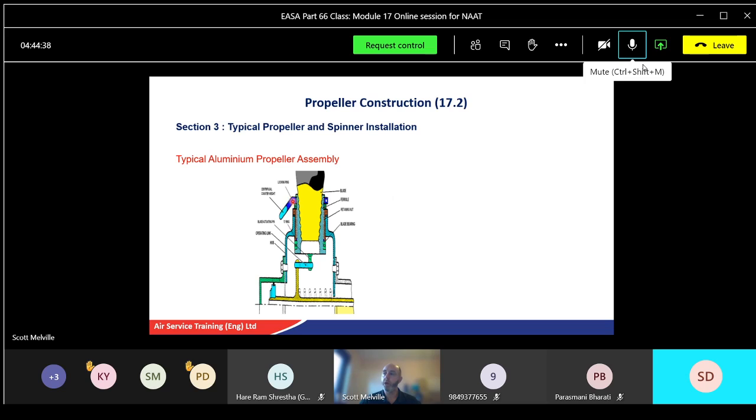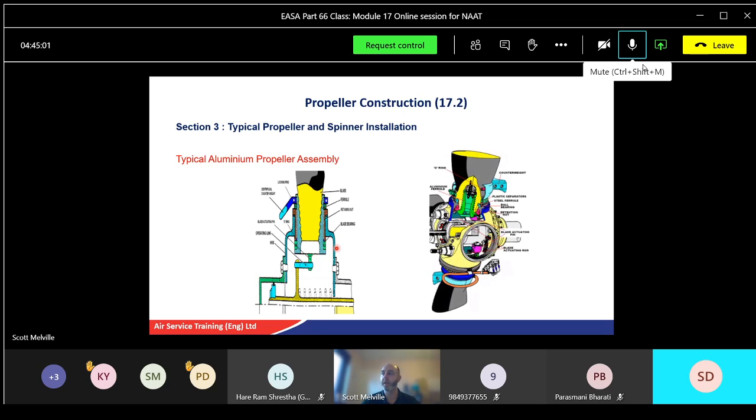There's your counterweight, and there's the locking ring. And you'll have your other bits of your change mechanism, and so on. There's the blade bearing, the one that will have your 30 ball bearings in there, and your plastic surround. There's a ferrule which it sits in, which the blade actually sits in as well. So you see why it's important that the nut must be shimmed to make sure it's the correct amount of torque and gap there.